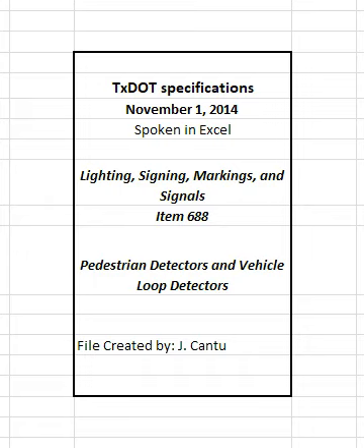3.1.2 Controller Unit. If a controller unit is required by the plans, integrate the pedestrian controller unit into the traffic signal controller cabinet assembly. 3.2 Vehicle loop detectors. Provide the loop location, configuration, wire color, and number of turns shown on the plans. Loops may be adjusted by the engineer to fit field conditions.